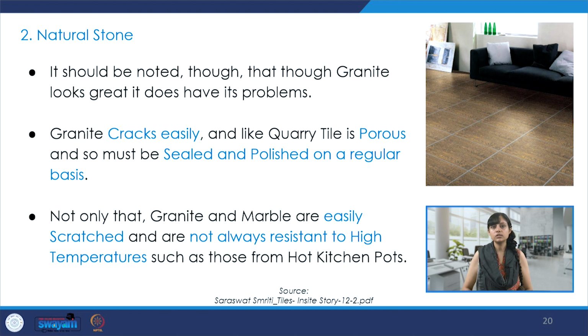It should be noted though that granite looks great, but it does have its own problems. It cracks easily. Also, like quarry tile, it is porous and so must be sealed and polished on a regular basis. Granite is also like that. And granite and marble are easily scratched and are not always resistant to high temperatures. So it is risky to keep hot kitchen pots and utensils on them.